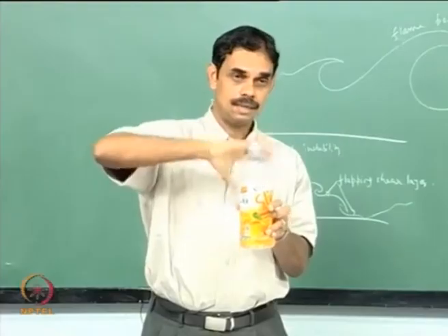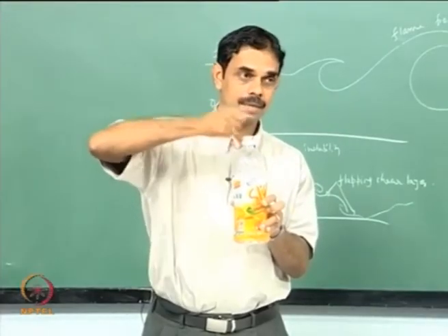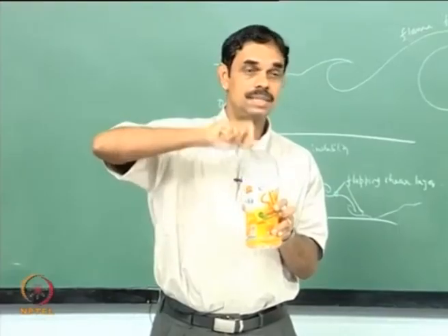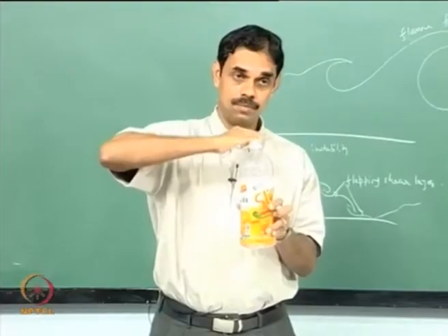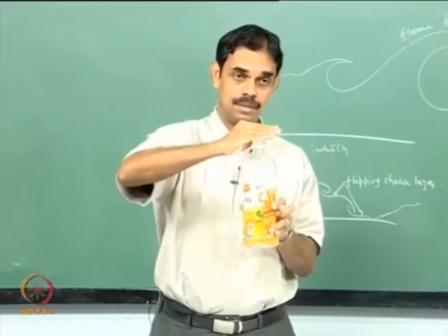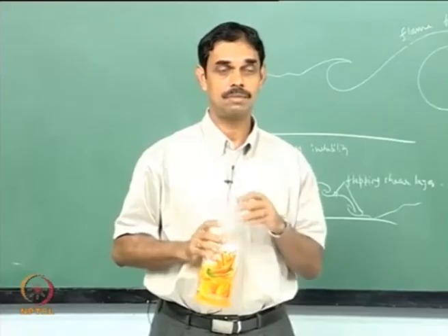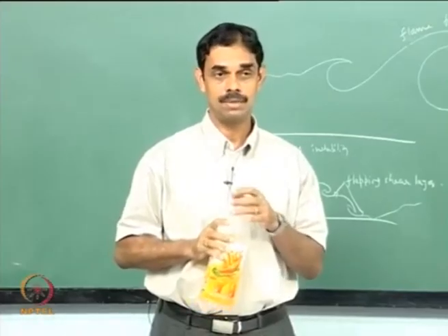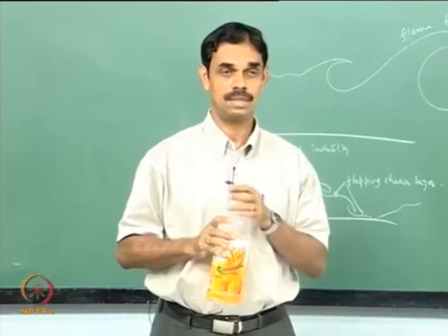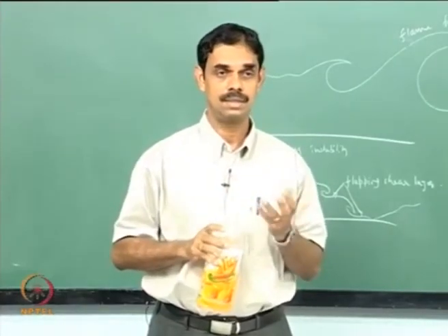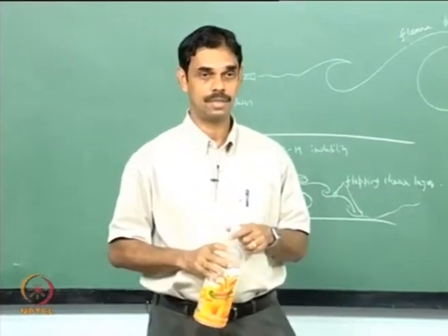Here the Helmholtz resonator has bulk oscillations which lead to velocity oscillations in this neck region, and the vortex causes this path. Then it makes sound, so aerodynamically you can have sound, but there needs to be some resonator associated with it, and this coupling has to be strong. That is one possibility you see in whistling, or in a flute, and so on.